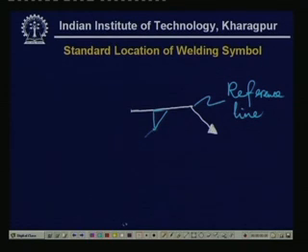If you want to apply it on the reverse side, then you will have to give a welding symbol. Maybe you may use two different kinds of welding, but proper symbols are to be given. So, the top one is the welding on the other side of the arrow of the joint pointed by this arrow. Both of them together mean that both sides are to be joined.